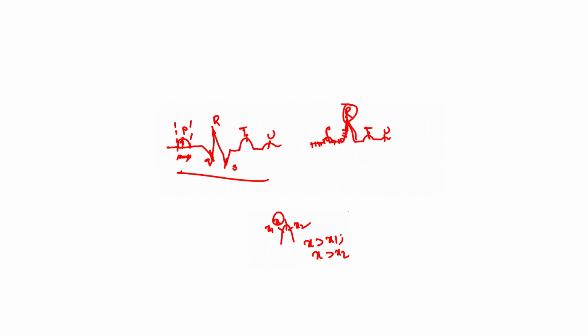So, if I put a threshold, out of the complete ECG signal, I find the maximum peak that I am getting, and in that maximum peak I fix some threshold somewhere around 70%, or around 50% of the peak. Like this threshold, so that it allows only the R peaks to pass through, and whichever peaks are below the threshold it will not allow. Then I can easily find the R peaks, and if I can calculate how many R peaks there are, my job is done.